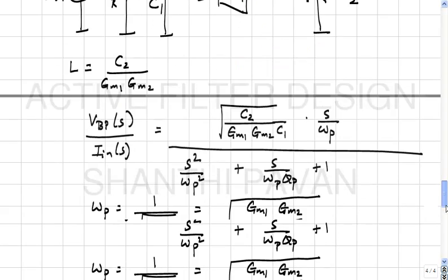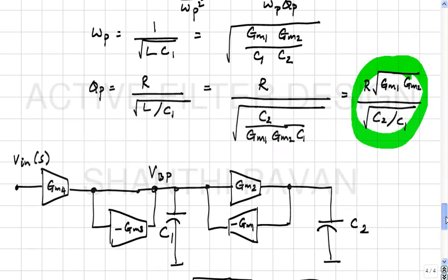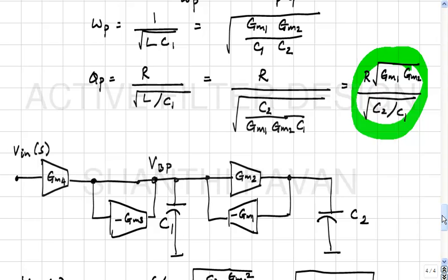All right, if you saw this for the first time, it would probably seem quite complicated, but now you know how you got it. This is basically taking a second order, I mean RLC parallel network, which you are all very familiar with, and replacing the inductor with a gyrator terminated with the capacitor, and the resistor with a transconductor, and the input current source with voltage source and a transconductance.